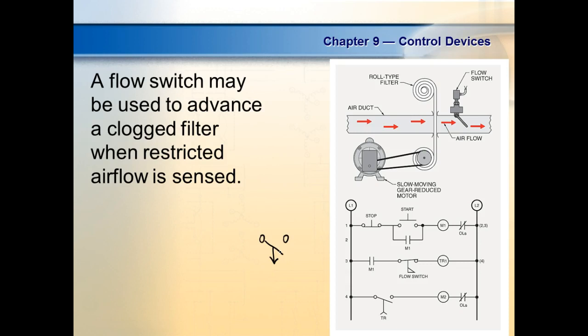So these are what we call non-retentive timers, which means what? If you de-energize them, if they're up to 4 seconds and you de-energize them, the next time you do it, it's going to start over. Right? Everybody understand that? So what else do we have in this chapter?